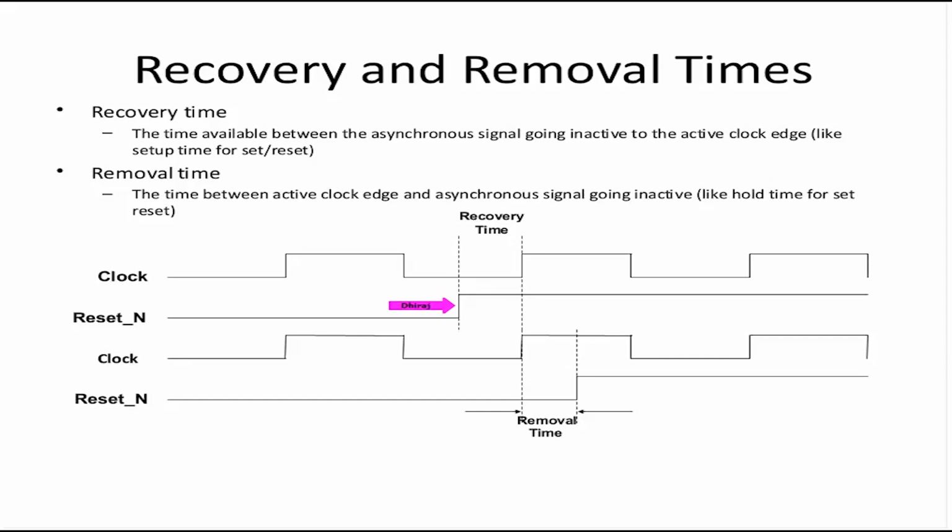Let's say you have an active low reset. Recovery is only characterized for reset going inactive, and not the other way. You can open up the standard cell library, go to a flop, and see how recovery and removal times are represented.